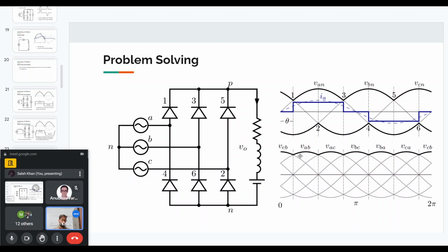So the peak voltage of the line voltages will be around 550 or 560 volts. That is much higher than the 240 volt battery. So that is why the battery will not play any part when the diodes conduct. It will not change the diode conduction starting or ending portion.